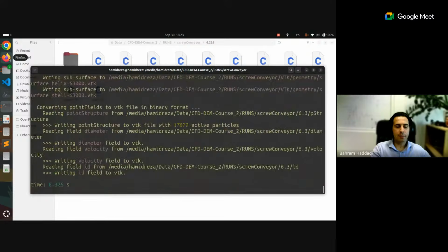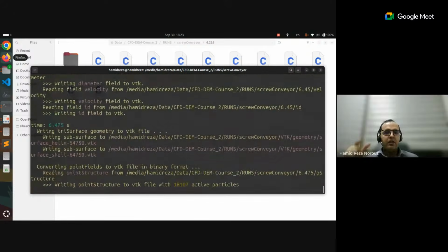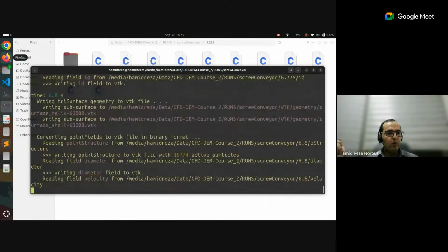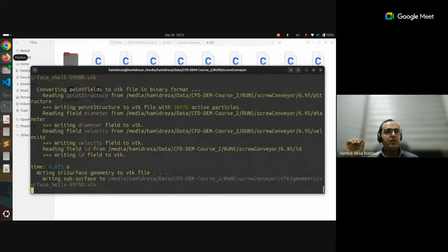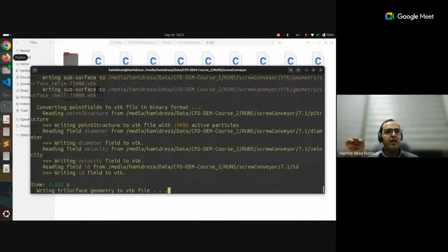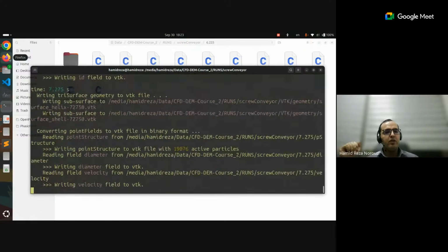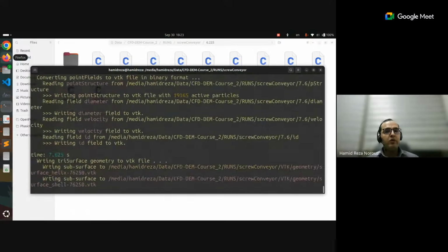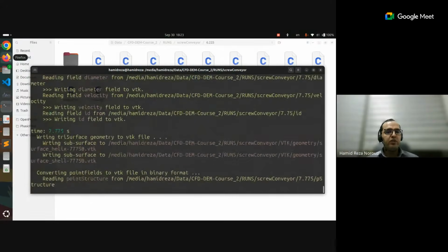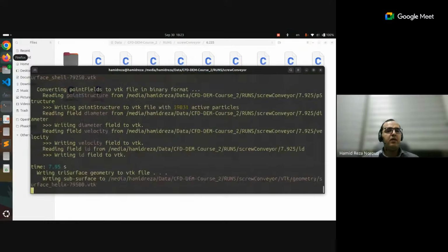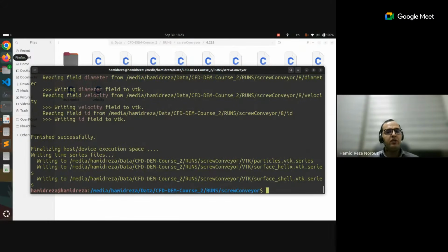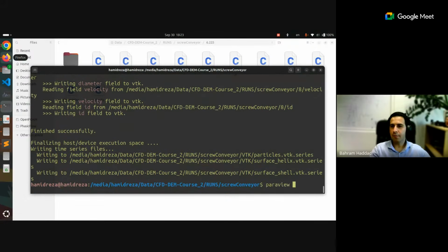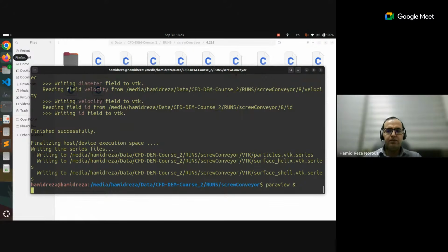So that's basically something which needs to come from the ParaView side. Since there are many users of OpenFOAM around the world, ParaView has this plugin as a standard plugin. So when you load that foam.foam in ParaView, ParaView knows that this is an OpenFOAM simulation, then calls the OpenFOAM reader in it to read the simulation results for you. Great, thank you. You're welcome.